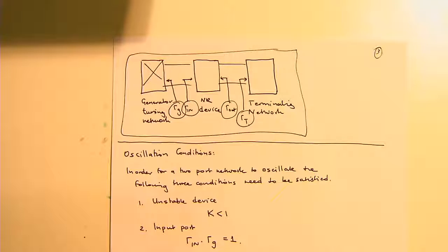Anyway, it's worthwhile. As a little homework exercise, look up negative resistance devices and look at some devices that can actually give you negative resistance. Of course, we're going to use transistors to give us some of these characteristics, but there are other devices out there which give you negative resistance in order to build an oscillator. You don't always need to use a transistor. You can use tunnel diodes, and sometimes vacuum tubes.